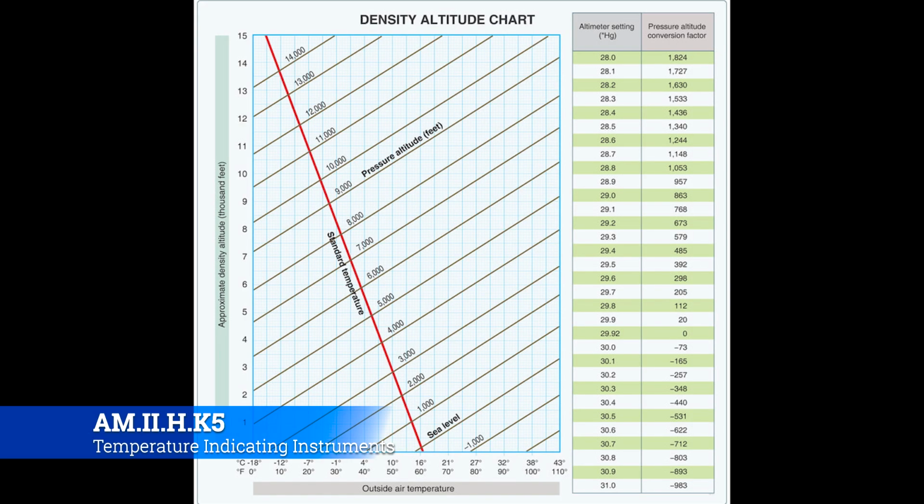But we're going to talk about the simpler one, that is temperature. Now, you might think, well, why is temperature a navigation aid? Well, temperature affects a lot. It will impact the density altitude of the air that the engine is taking in. That's changing the amount of fuel that we can put inside of that fuel-air mixture, which then affects our performance.